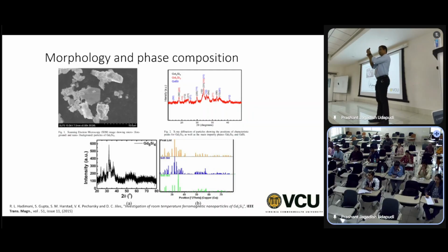You use some electromagnetic coils to focus and accelerate those electrons, and when these accelerated electrons hit the sample, a lot of them are reflected back from the nucleus of the material, and some of them are reflected from the surface. Some go to 2 nanometers depth, some go to 15 nanometers depth. Depending on how deep they go, you get different types of scattered electrons.